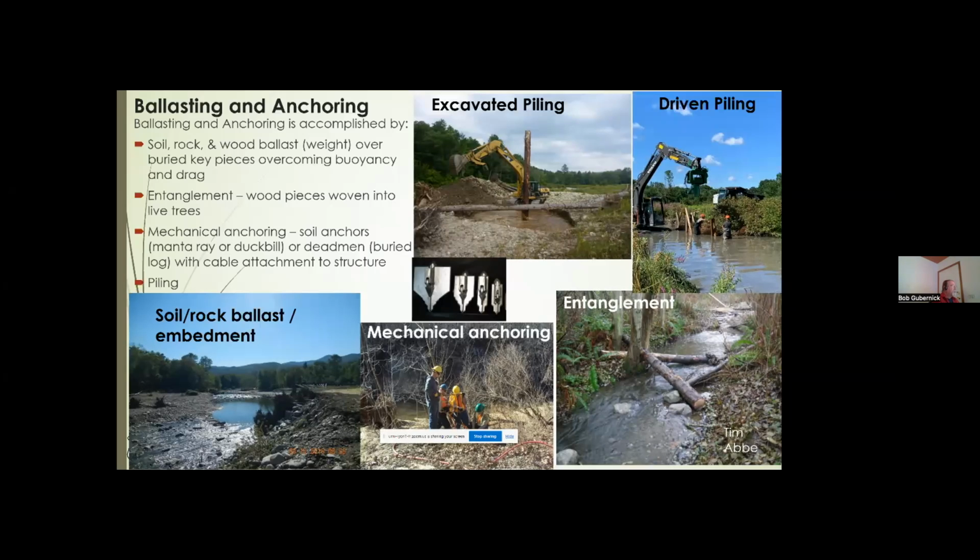You can use piling. Piling are great. When you're putting piling in a gravel bedded, cobble bedded river, it's a slow process. You have to excavate large holes. That piling that you can see in the middle photo actually has the root fan attached and is essentially about 10 feet below the water line there to help resist the forces on the structure that we're building. If you're in finer grained sediments, fine gravels, sands, cohesive materials, you can drive piling in, as you can see in the upper right-hand photo.